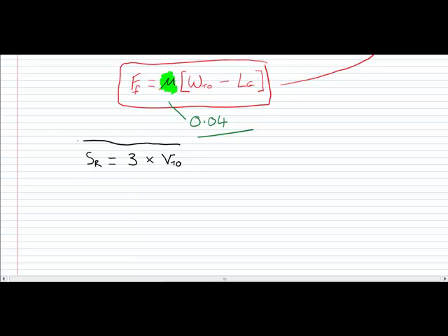So although the ground roll component involved complex integrals, the rotation component assumes that for those 3 seconds the aircraft is effectively travelling at the takeoff velocity. In reality, of course, it will be accelerating through those 3 seconds. But just to make life easy for ourselves, we'll simplify it to that.